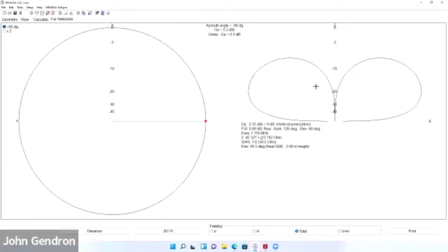elevation plan. Okay. So this is showing your elevation from ground level up to vertical. Okay. And remember we said that lobe where we were at, where maximum gain was at 26.5 degrees, right? So you can see where that thing reaches out here as farthest point. It's right at between 27 and 26 degrees. That all make sense to you?